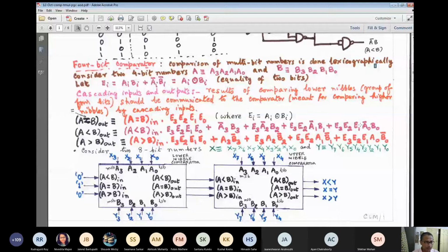So that means we have to look for 5 distinct conditions, and overall, in totality, they will be mutually exclusive. That means if suppose the first condition holds good, then the other 4 are false. What do you mean by the first condition holding good? It is that this is 1, in addition to bitwise equality. So for that I have got this logical way of putting the condition. The second condition is very crisp. It only says whether A3 is less than B3 or not.